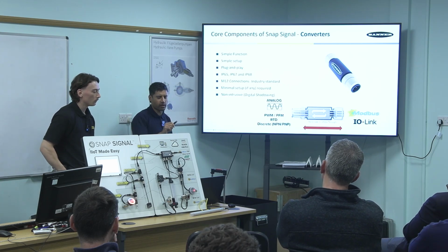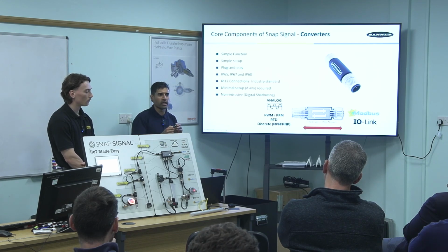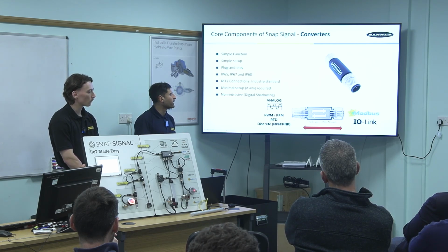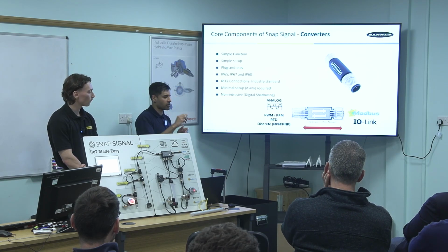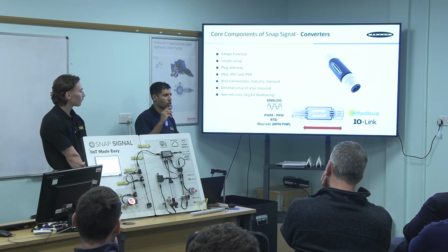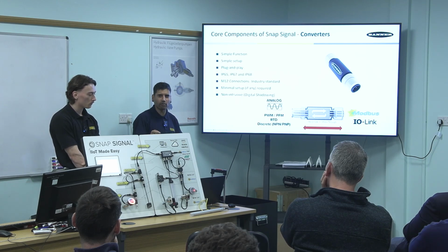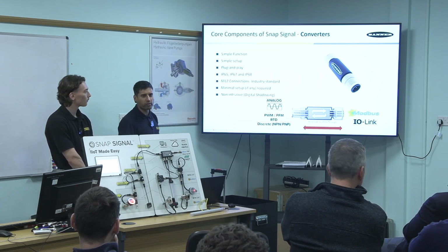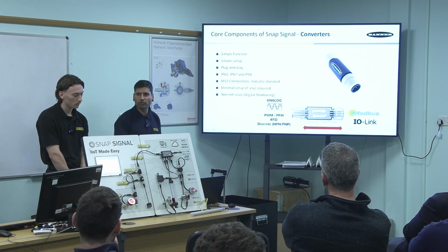And within it, for example, the discrete signals, we've got Modbus registers within there, which can automatically calculate events per minute. You can switch from NPN to PNP just by making a parameter change. There's a totalizer in there, a counter in there. You can mirror. The discrete has got a 2 in, 2 out, or it could be 1 in, 1 out, if that makes sense. So you can mirror an input coming in to an output, and that's all parameterized via, you could even use Modbus Poll. You don't have to use our software or anything.